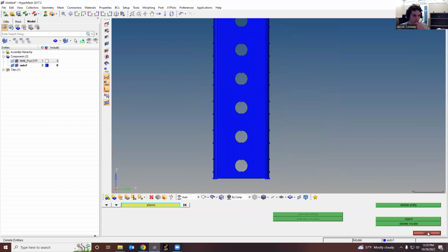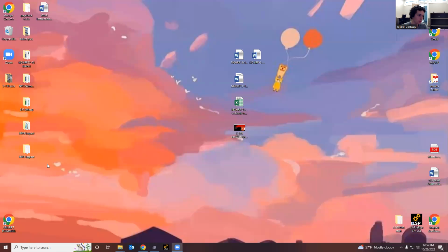So yeah, my previous one, I used a 0.5 size mesh, but I used a different technique and it turned out all right. But again, if you have too large a mesh, you're not going to get the details you want. So I actually ended up having a diamond shape hole right here, which isn't awful, but the minimum you're going to want for a hole is like a hexagon. You're going to want at least 6 sides to that. I only had 4. The mesh looked good. I can actually pull it up for you right here.